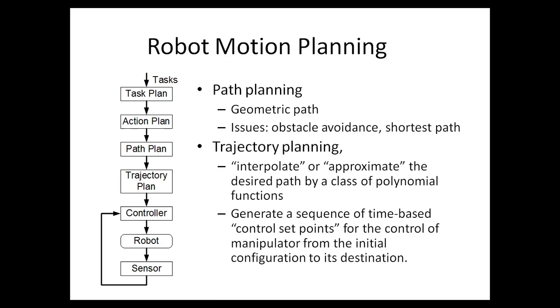Path planning is actually the process we usually use to construct a path from a starting point to an end point, given a full, partial or dynamic map. Whereas motion planning is the process by which we define the set of actions which need to be executed to follow the path that we had planned. Okay, so this is the difference between path planning and motion planning.